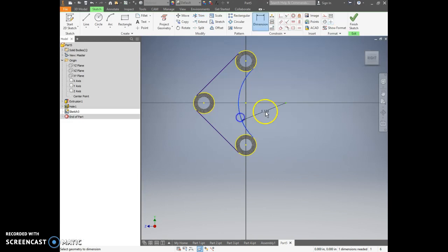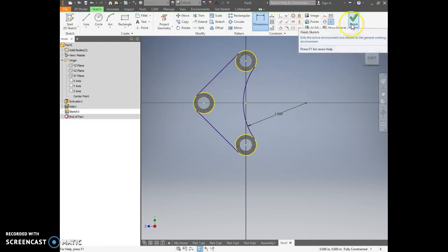And then I go ahead and dimension my arc. They tell us in the book what that is. It's a 1.5 dimension. And it should have that all fully blue as soon as you do that. So as long as you have your two sides of it tangent, trim it out, dimension it with the radius there of 1.5, you're good to go. And here, you might think you draw the other part of it in there, but you really don't. It's better to draw this here, make a positive feature, and then do all your cutouts in it. That's kind of the correct procedure for Inventor. It'll make things better when you do more complex things later.